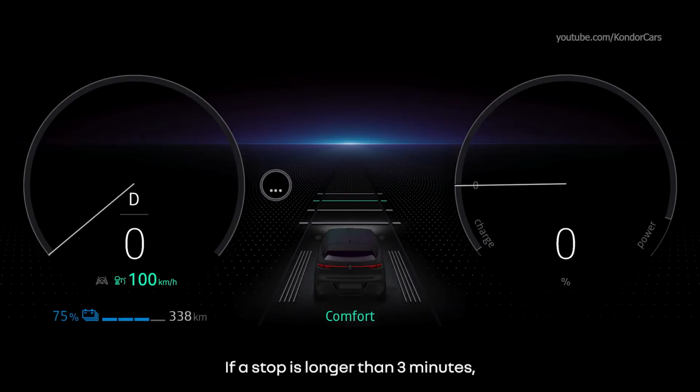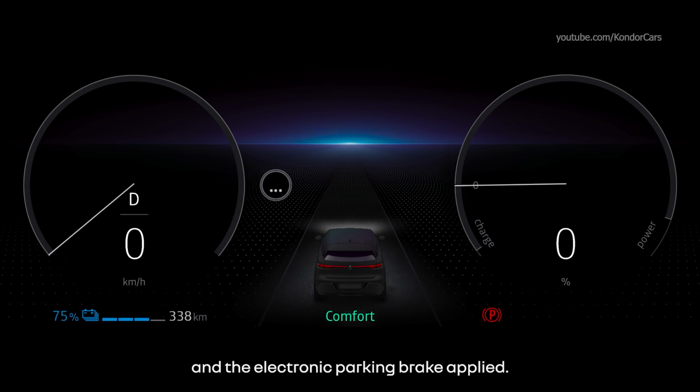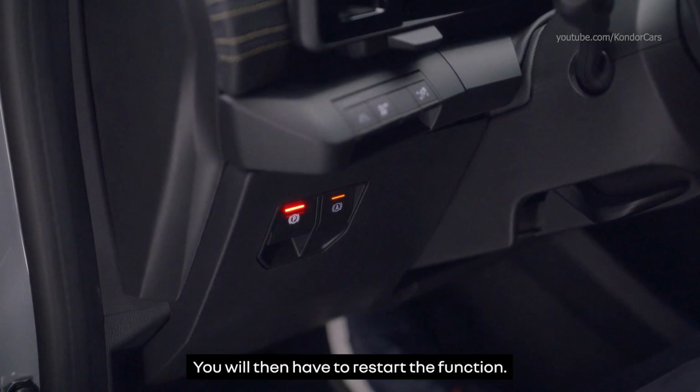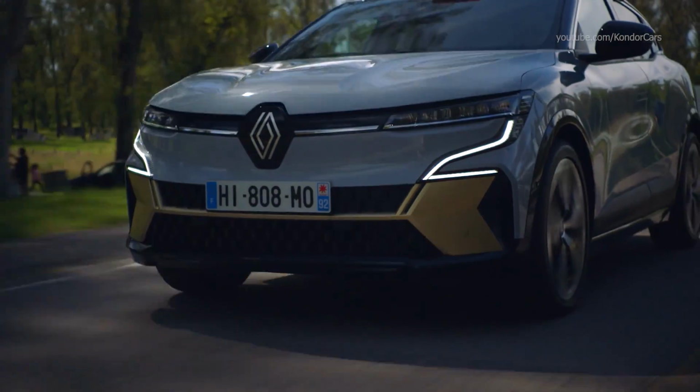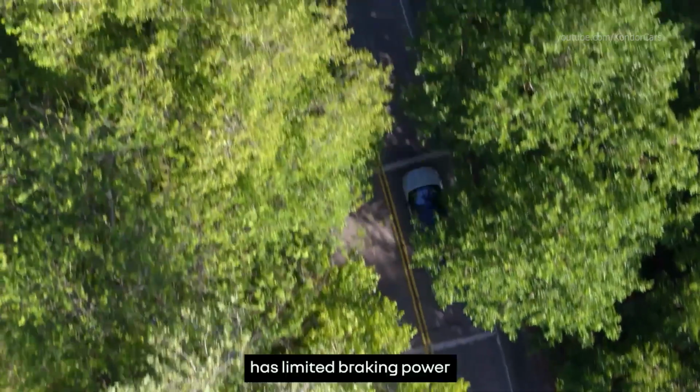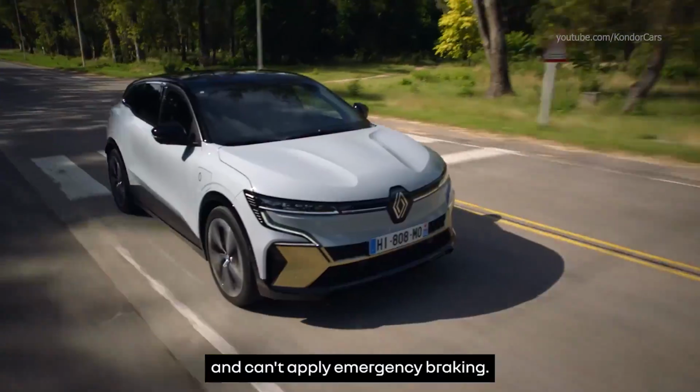If a stop is longer than 3 minutes, Active Driver Assist will be switched off and the electronic parking brake applied. You will then have to restart the function. Bear in mind, though, that Active Driver Assist has limited braking power and can't apply emergency braking.